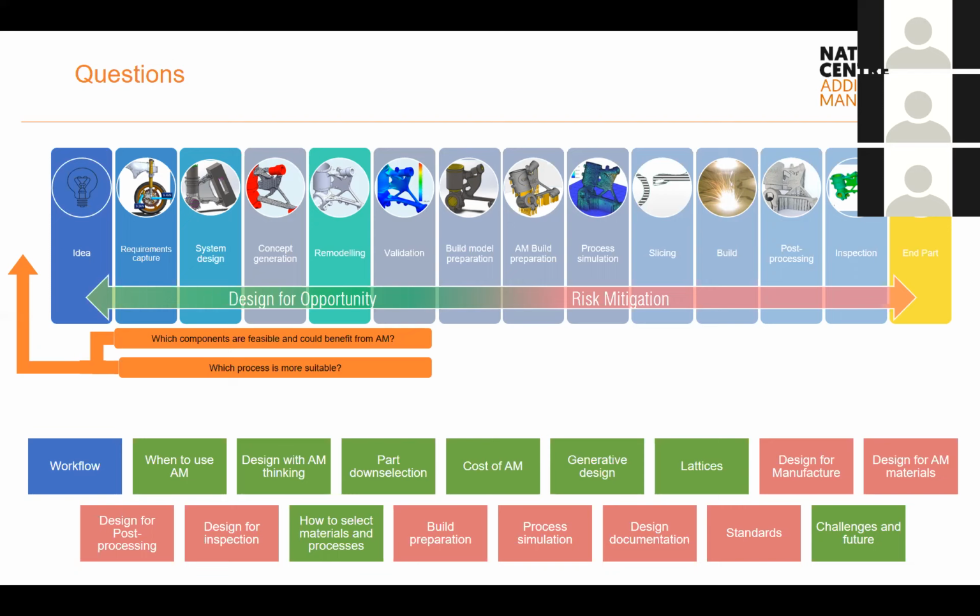In terms of the process simulation, the tools are still developing, so there are some technologies that are more developed than others. But we can think that in the post-processing, depending on which technology you are using, it will be completely different. Thinking about technologies that are very different, for example, in the slicing, in extrusion-based or desktop printing you prepare the toolpaths of your head, while in powder bed what you prepare is the hatching on each layer with your laser. In some ways similar, but there are many different things that need to be implemented in the remodeling step.